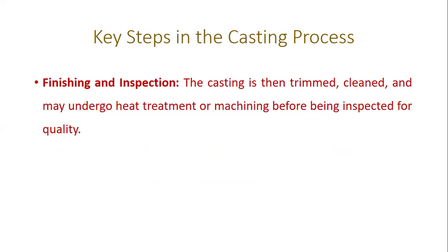The final casting is then trimmed, cleaned, and it may undergo heat treatment or machining before being inspected for quality. So this is called finishing and inspection.